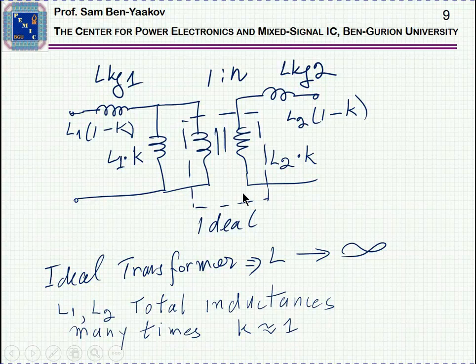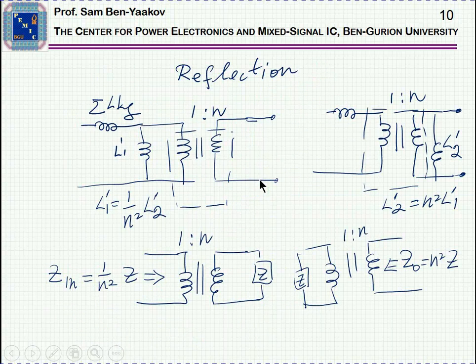This transformer really doesn't have any characteristic of impedances that you are interested in. It just serves to do the transformation between voltages and currents like an ideal transformer. So we'd like to make these impedances, that is the inductance of this ideal transformer, very large. And of course you use K equal to 1 because now this is an ideal transformer. The transformer is this thing altogether. This is just the heart of this transformation between currents and voltages.